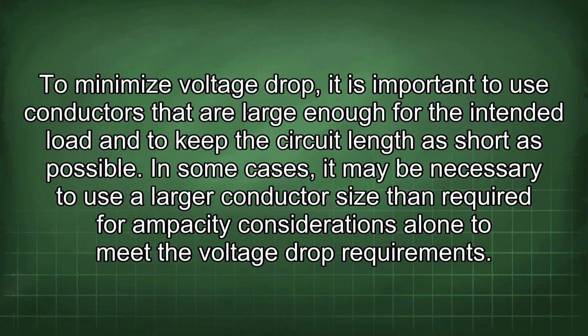To minimize voltage drop, it is important to use conductors that are large enough for the intended load and to keep the circuit length as short as possible. In some cases, it may be necessary to use a larger conductor size than required for ampacity considerations alone to meet the voltage drop requirements.